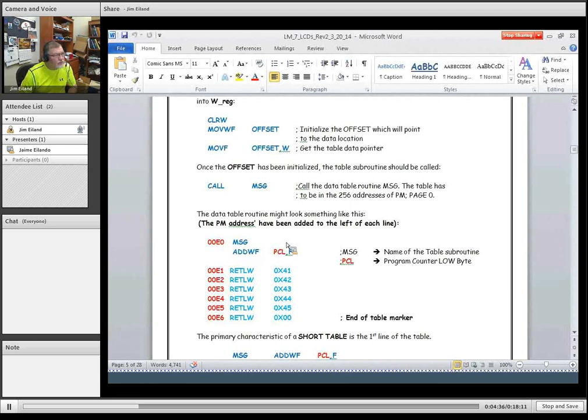If you recall, the program counter is set to 0 when you power up, and after each instruction fetch, it is incremented. So it always contains the address of the next executable instruction. It's often changed when you call a subroutine, and you have to be aware of it if you're going between pages of memory.